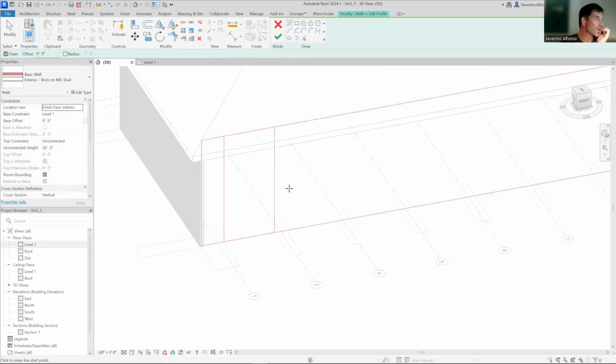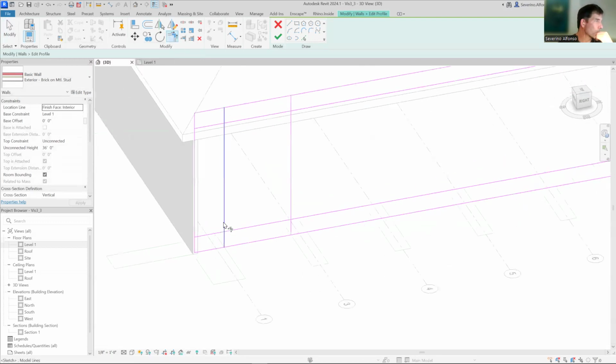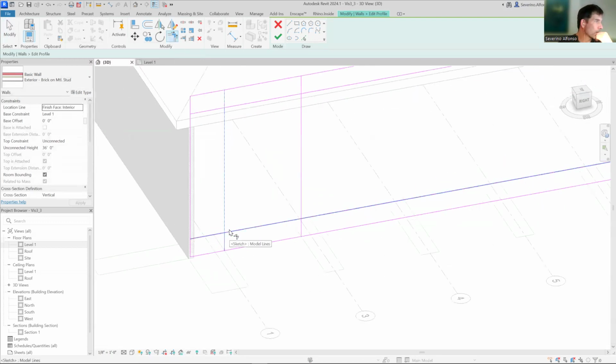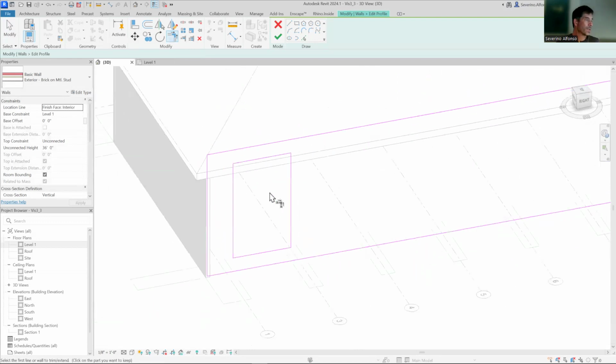I can't just insert anything because, again, it's not a standard element. So I'm going to create those lines vertically. I'm going to do an offset, Alt-F, of 4 feet. So coming down and 4 feet coming up. TR is this command, which is the trim extend. The way it works, you click on one side of it and another one, and it creates that fillet condition. And I can repeat that command as many times as needed.